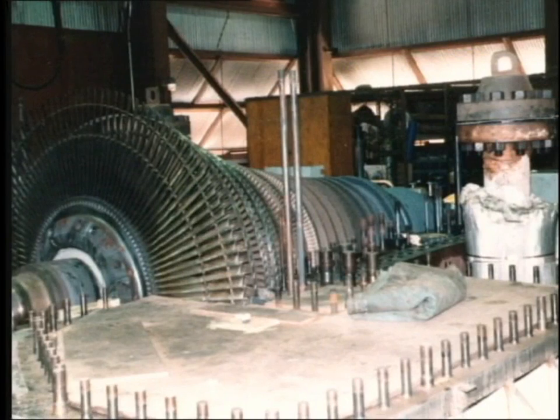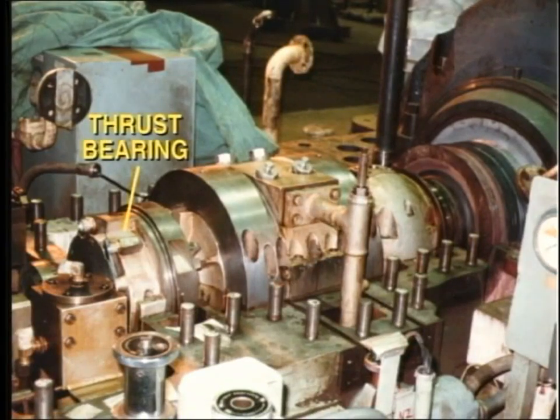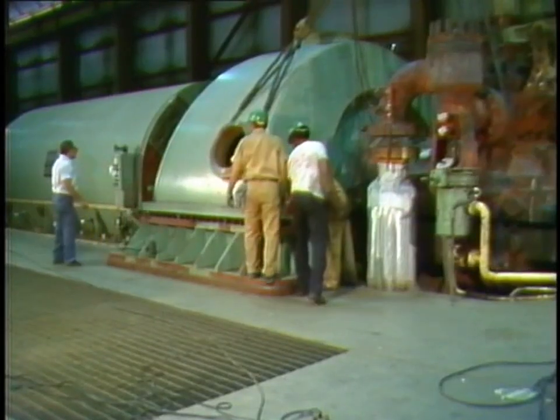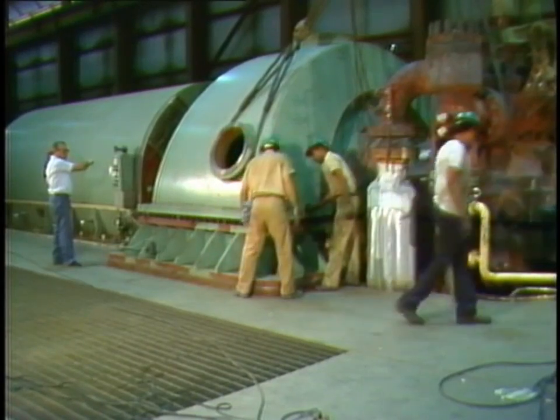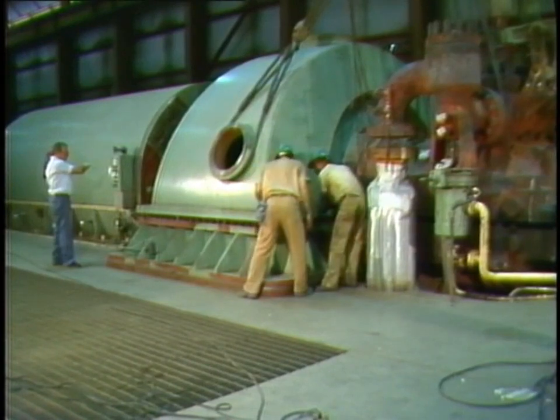When the turbine is assembled, the rotor must be very carefully lowered into place so that the discs fit perfectly between the respective diaphragms. Once the rotor is in place, the axial clearance can be adjusted and finally fixed in place at the thrust bearing. Similarly, the journal bearings must be adjusted to provide correct alignment with the generator rotor. When all adjustments are complete, the top half of the casing, which is a mirror image of the bottom part, is very carefully lowered into place and finally bolted down.